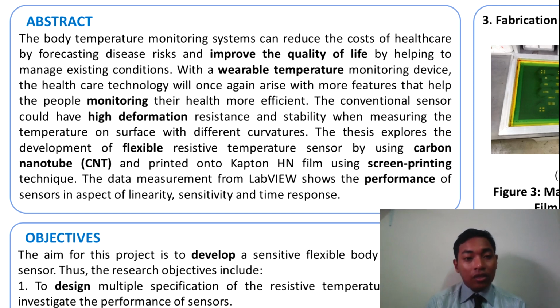The thesis explored the development of flexible resistive temperature sensor by using carbon nanotube (CNT) and print onto the flexible substrate which is Kapton HN film. Few design of serpentine structure were designed with specification to achieve high sensitivity of sensor. The result obtained from LabVIEW show the performance of sensors in aspect of linearity, sensitivity, and time response.